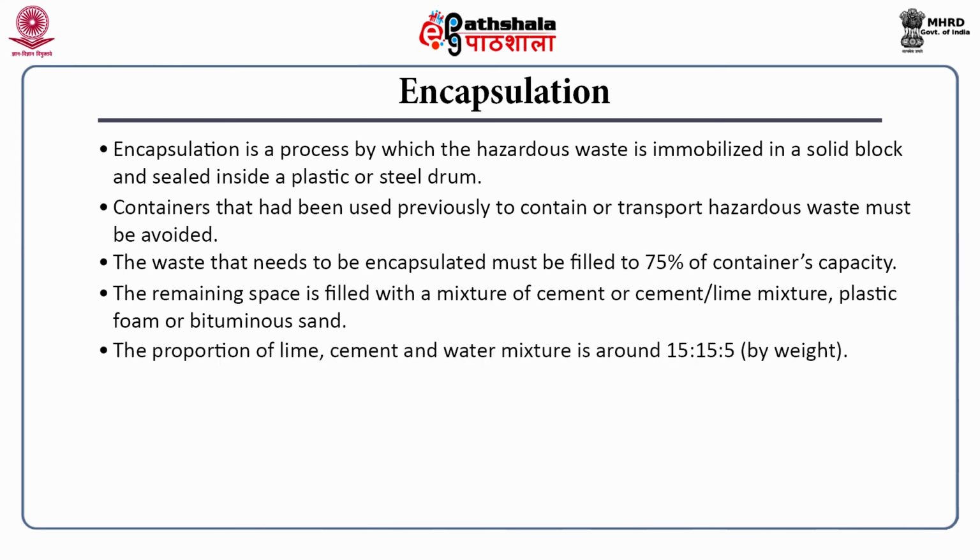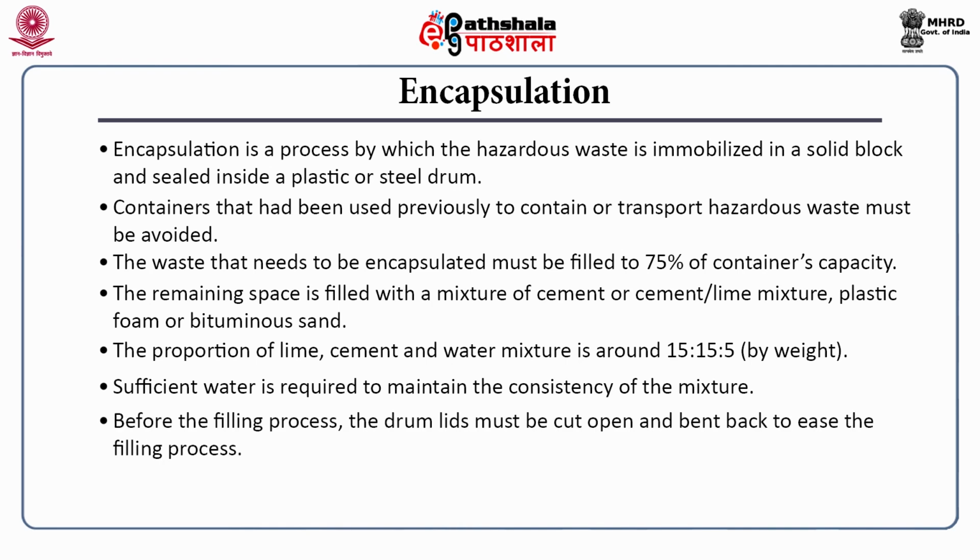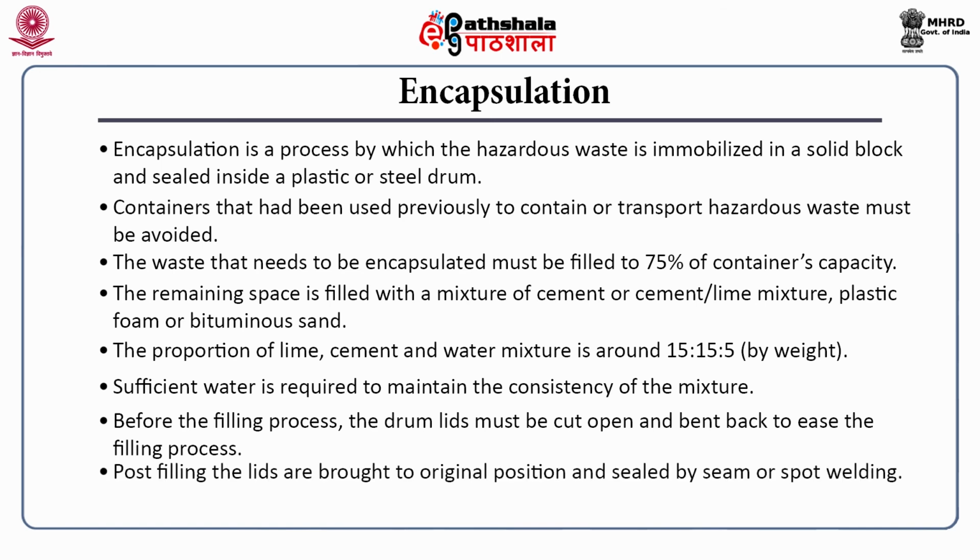The proportion of lime, cement and water mixture is around 15:15:5 ratio. Sufficient water is required to maintain the consistency of the mixture. Before the filling process, the drum lid must be cut open and bent back to ease the filling process. Post filling, the lids are brought to original position and sealed by seam or spot welding.